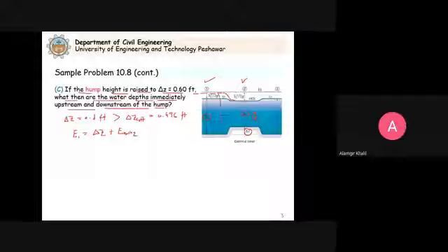So you can see here that now Y is different. This is now Y1 that we have to calculate. This is due to the damming action. This effect here is known as the damming action, as we discussed. When the height of the hump is greater than the critical hump height, it will result in damming action. The height of the water on the upstream will increase. Clear? So that's why we have E1 and Y1 is unknown.